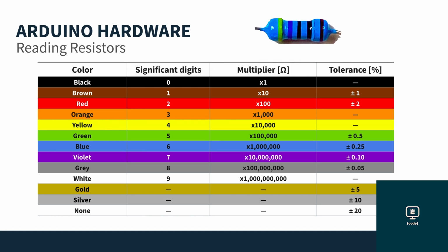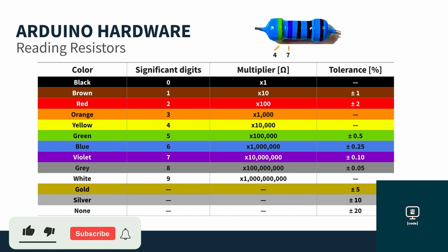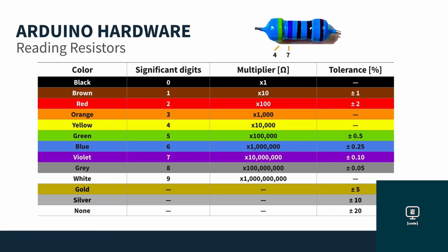And here's the other. You can see the first band, in this case it's a 5-band. It's starting with yellow for 4. Then it's a little hard to see. The resistor itself is blue in color, but the band is actually violet. And it's a little hard to see that, but that is the actual color, sort of a violet. With the printing of resistors, the quality of the colors can really vary. The next band is black, which is a 0. So 470 is what you're starting with for the significant digits.